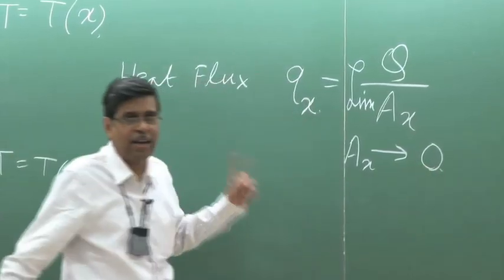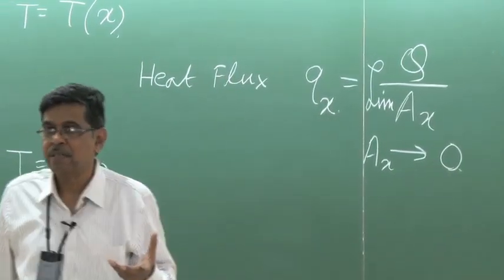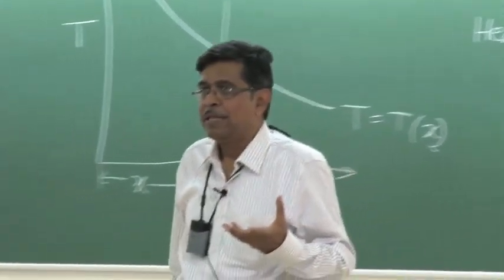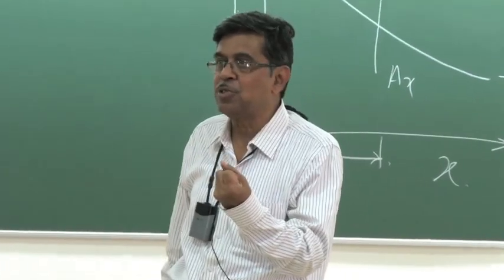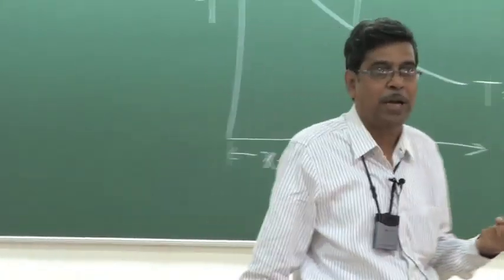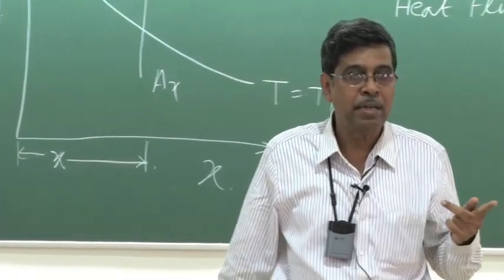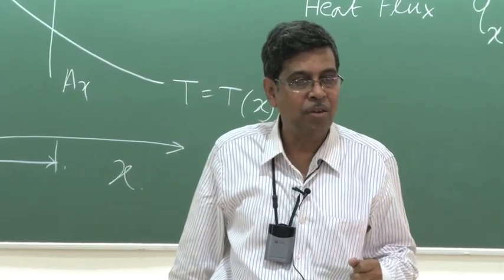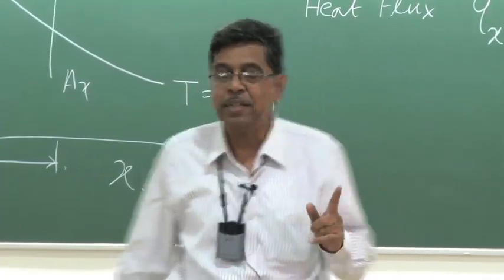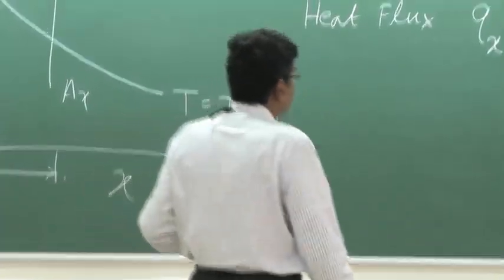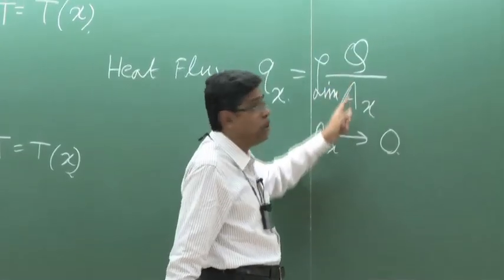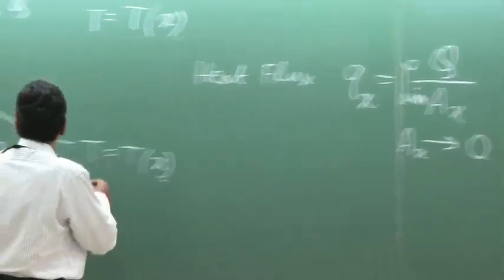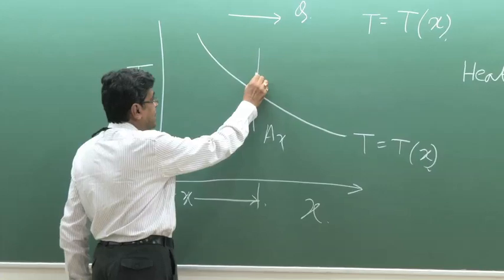Now it is very fundamental and basic, like the stress, that the heat transfer reduces to 0 when A reduces to 0 at a point, but their quotient attains a finite, limiting value, and that is the heat flux, that is the amount of heat per unit area, and therefore this gets a definition at a point.